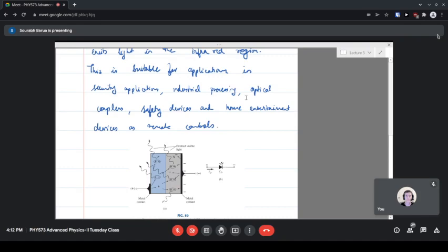And similarly, you have optical couplers, meaning there is exchange of information using light. For example, your source is an LED, which can be an infrared LED, and your photodetector will also be an infrared photodetector. So basically, the light signal from the infrared LED will be detected by your photodetector, and so this unit together will be an optical coupler.